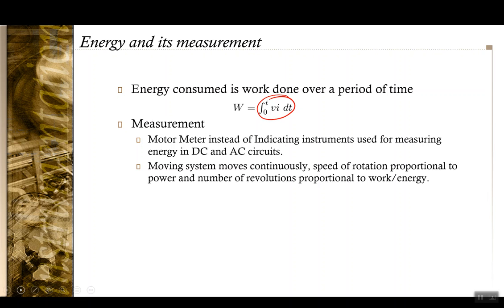That is, it is not supposed to give the instantaneous value, but it is supposed to give the integrated value over time. And for this purpose we would be using motor meters instead of indicating instruments. And it doesn't matter whether we are doing it for AC circuits or DC circuits.